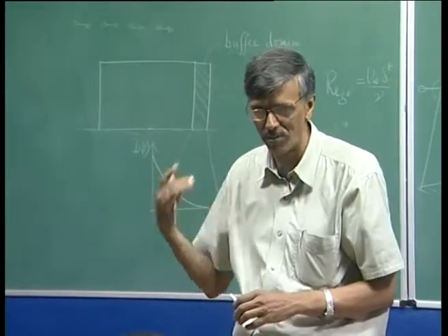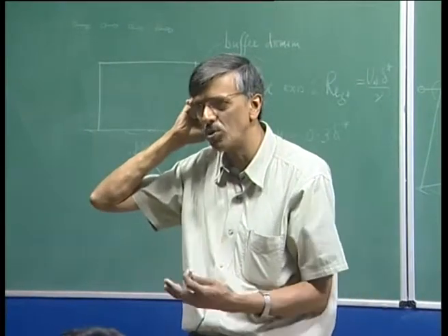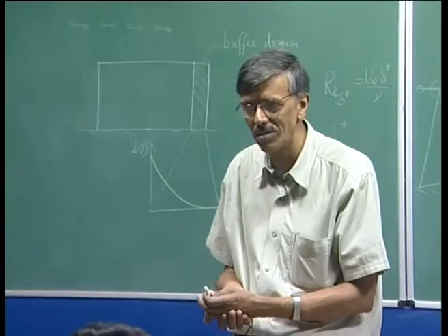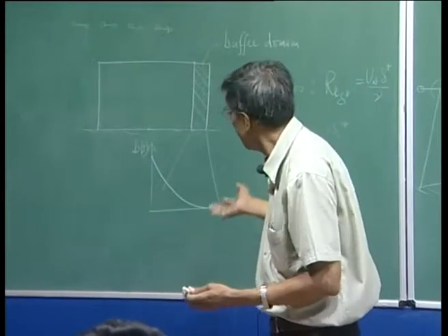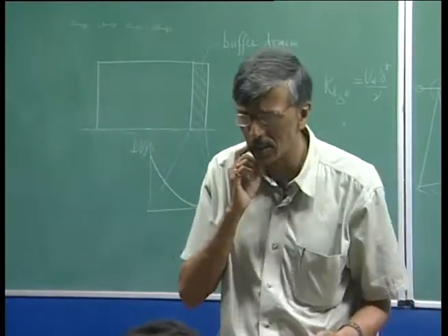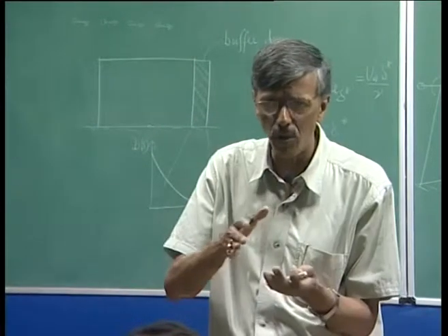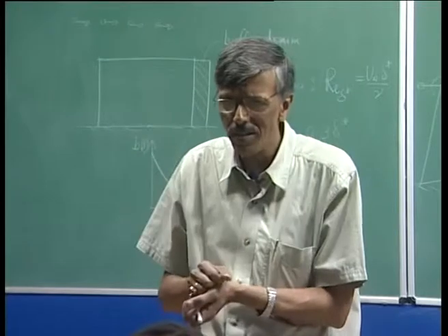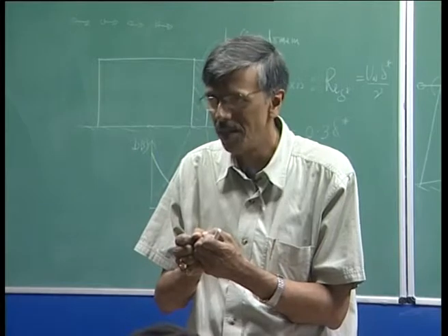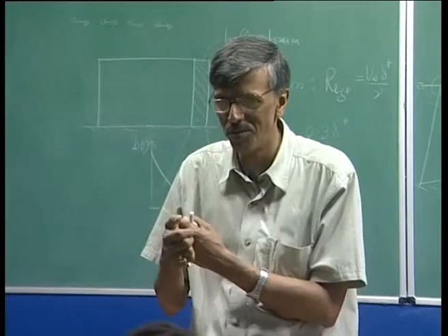That was the reason that we proposed this model, and we wanted to show the receptivity of the shear layer to periodically convecting vortices. You would see an identical scenario, and it's quite relevant that if you are looking at an internal flow inside a turbo machine, the vortices shed from the rotor will be essentially viscous vortices. They will not go at c equal to u infinity.